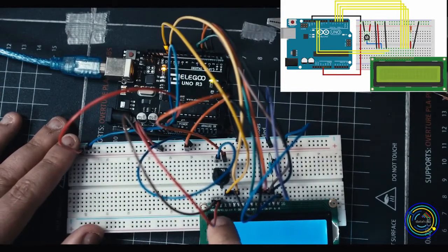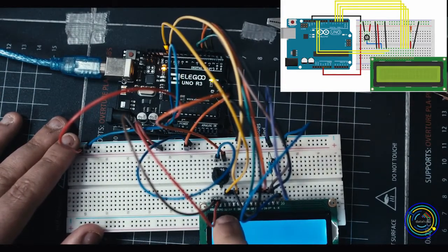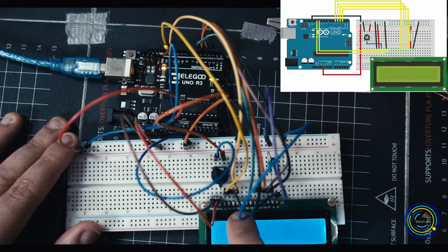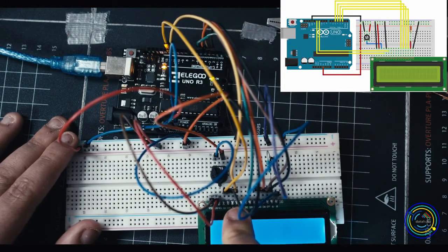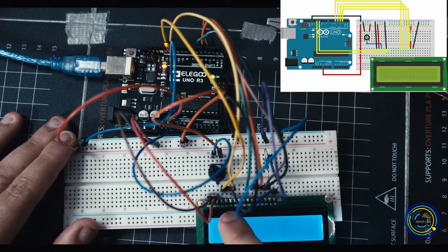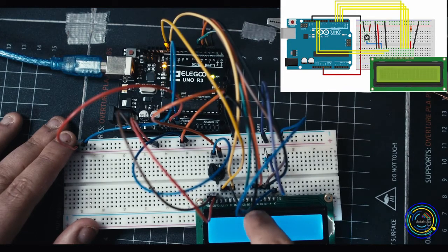First pin goes to ground. Second pin goes to power. Third pin goes to potentiometer and gets split into 2 pins. One going to power, one going to ground. Then we got a yellow cable going to 12 on the board, a black cable going to ground, a yellow